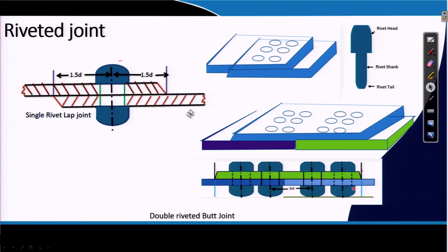Now, why exactly are those bridges riveted, not welded? Because bridges and all that undergo a lot of vibrations. Wherever there are huge vibrations, the best way to give a permanent joint is the riveted joint. The riveted joint can be made in two ways.